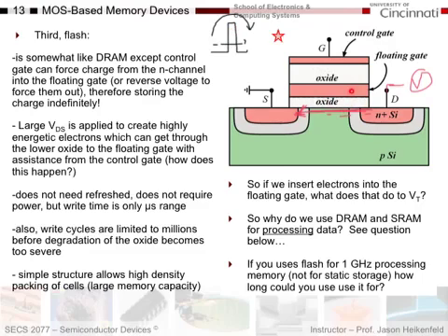So that's a limitation. One of the advantages of this is that this is just one transistor to store a bit. How beautiful is that? Meaning that I can get very high density memory on a chip. That's why flash drives can get such high densities, because each bit just requires one transistor like this, where it's got its storage and its transistor readout all in one device. So you get large memory capacity.